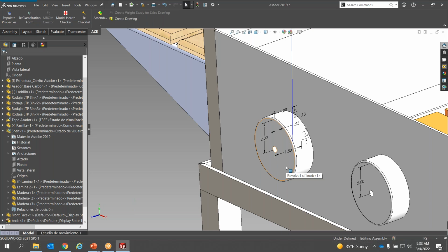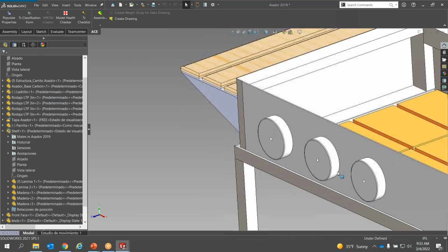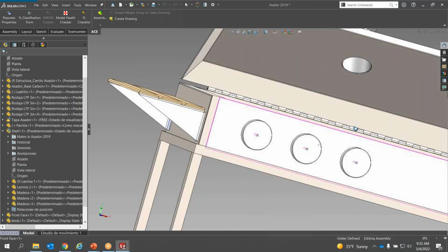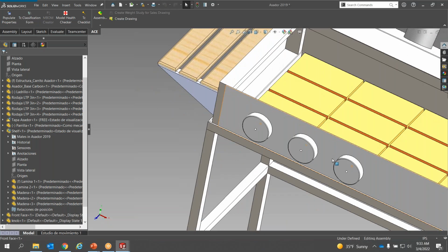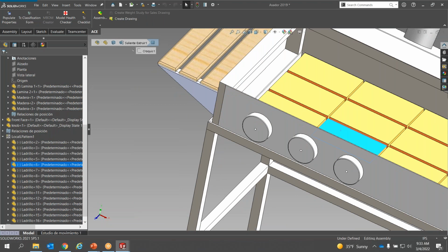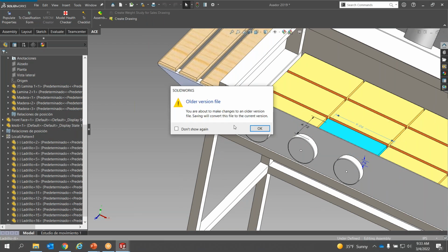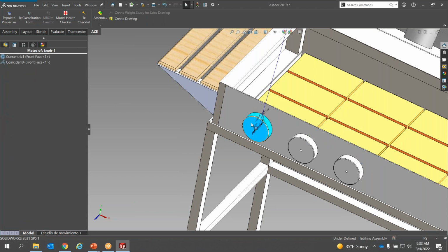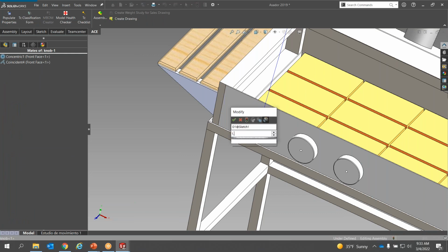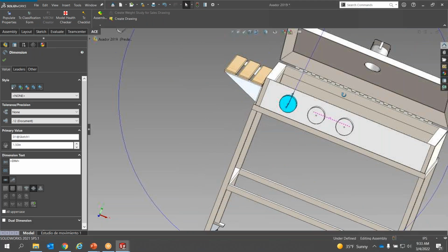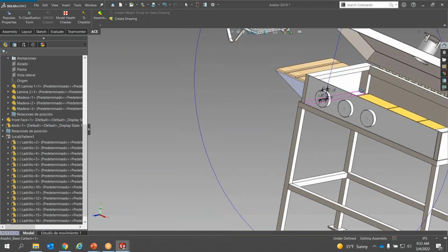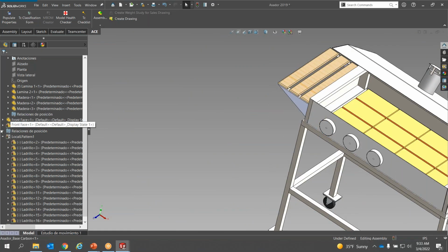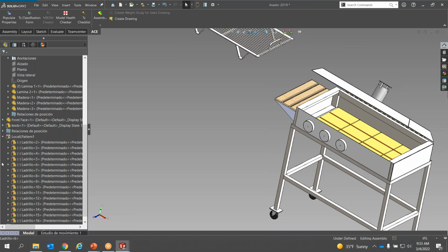So we're going to do our Control B command, and it only rebuilds those 2 things that I've changed here, or the 3 parts that I've changed, because that's the only difference I made. But let's say I want to change this up again here, and we're going to make it 8 inches. And we're going to take this and put it at 1.5 again. As you can see, nothing's changing. All of it's still ready to rebuild. And you see over here, you got your little stoplight rebuild button on everything that needs to be rebuilt.